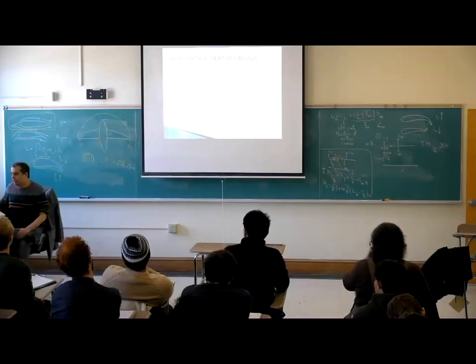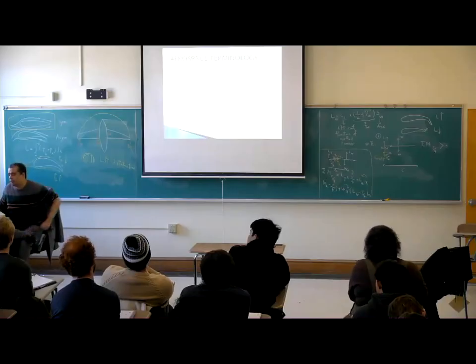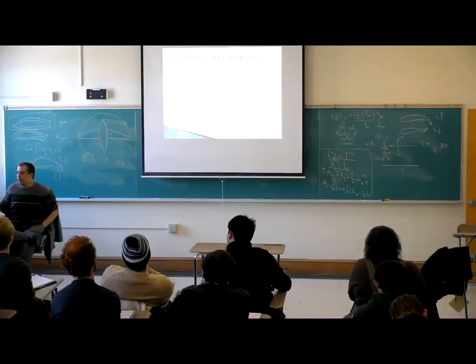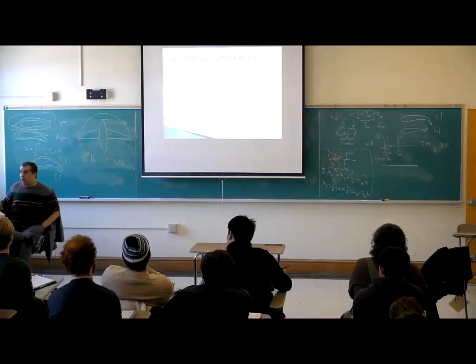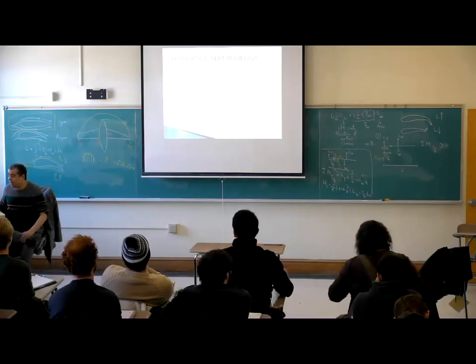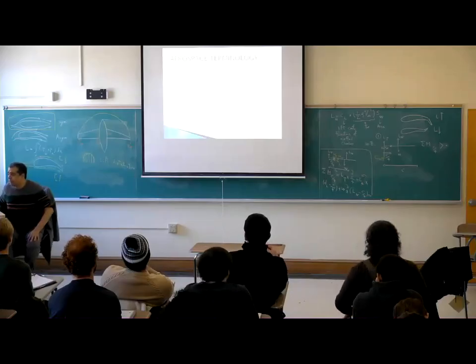Gross weight: the nominal weight for a standard mission before the aircraft takeoff. So gross weight is the crew weight plus payload weight plus fuel weight plus empty weight. It is the gross weight. So when you buy an airplane from a company, it gives you all these details, especially for a lightweight airplane, it should be very important. So these are some general information, and these are some aerodynamic and propulsion information.